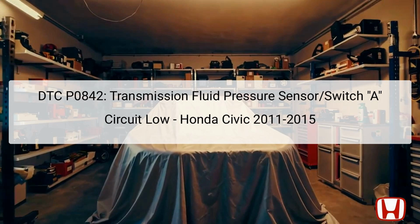The primary components associated with this error include the transmission fluid pressure sensor, which is responsible for providing the engine control module, ECM, with data on the transmission fluid pressure. This sensor is located on the CVT-driven pulley, which plays a crucial role in the automatic selection of gear ratios.